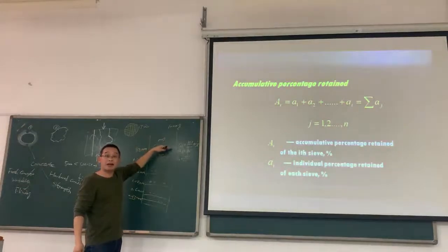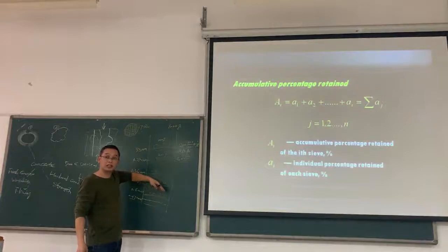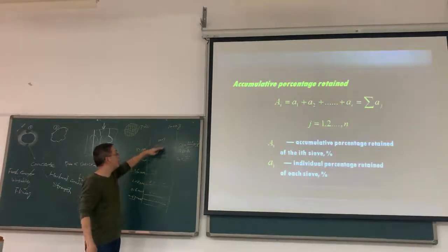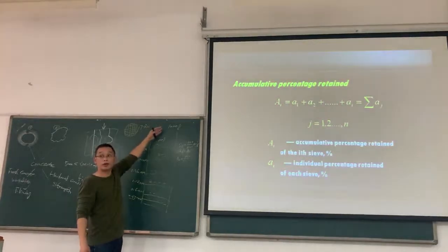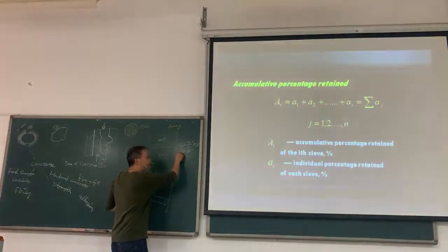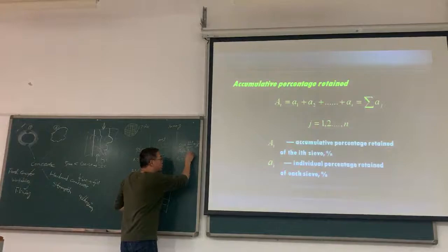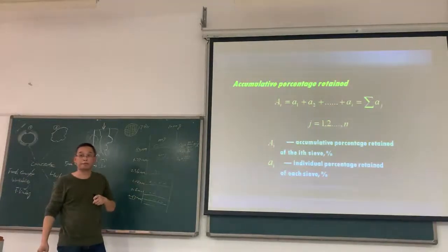If the size is bigger, it moves up. But there is no sieve at the top, so the accumulative percentage retained equals the individual percentage retained.